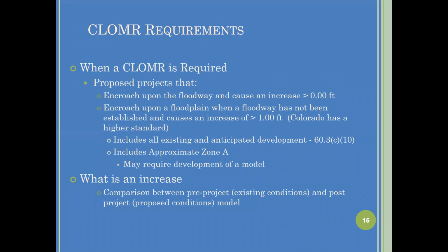Oh, okay. Right. And a nuance on Caitlin's earlier question, tying into what Diana just said: if someone is filling in the flood fringe, technically a CLOMAR is not required at that point. It's when they go into the floodway and you don't achieve a no rise, which will be covered in a later unit, that a CLOMAR must be done.